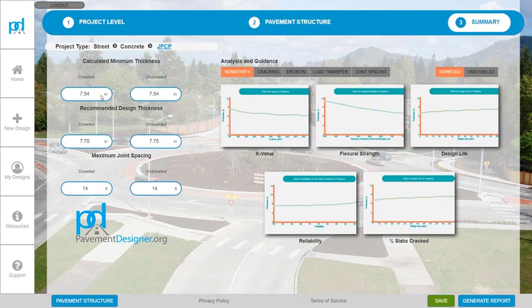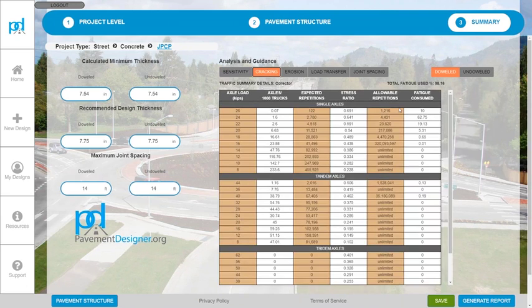And when they're equivalent, we know that our pavement is failing by cracking. You'll notice, as we showed in parking lots here, that when we're consuming the fatigue life or the cracking life of our pavement, then we're failing by cracking. And that basically means that while those dowels may be there and help reduce any erosion that might occur, they're not really providing a huge benefit on the cracking life, and so these designs are equivalent. That's not to say there won't be benefit from having dowels, it's just not the critical factor in this particular design.